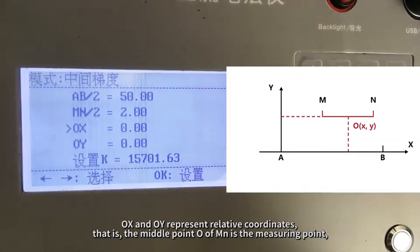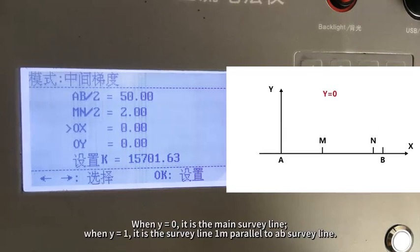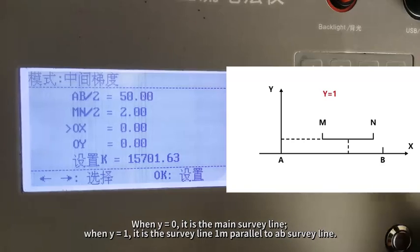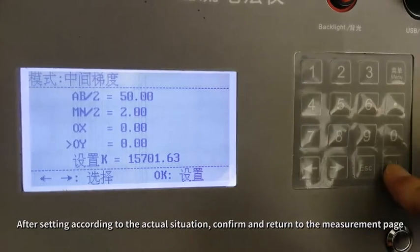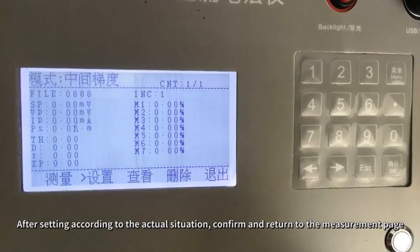O, x and O, y represent relative coordinates, that is, the middle point O of MN is the measuring point. AB is the x-axis of the coordinate axis, and the y-axis data is the parallel distance between MN and AB survey line. When y equals 0, it is the main survey line. When y equals 1, it is the survey line 1 m parallel to AB survey line. After setting according to the actual situation, confirm and return to the measurement page.